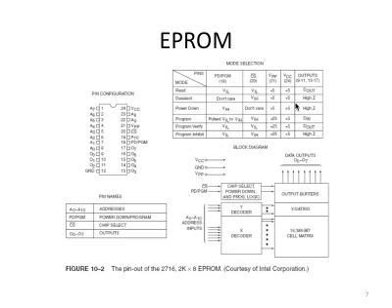So if you look at this pin configuration diagram, you can find that from A0 through A10, you have 11 pins for the address. From O0 to O7, you have 8 pins for data.